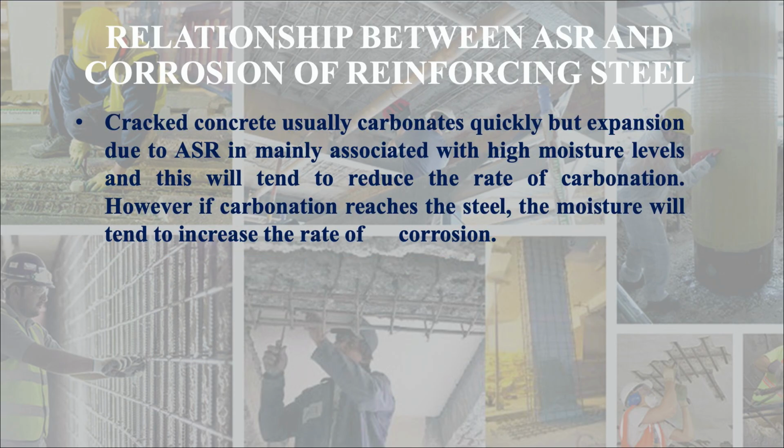Number two, cracked concrete usually carbonates quickly, but expansion due to ASR is mainly associated with high moisture levels, and this will tend to reduce the rate of carbonation. However, if carbonation reaches the steel, the moisture will tend to increase the rate of corrosion in that case.